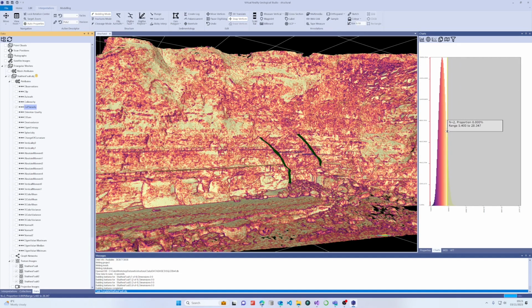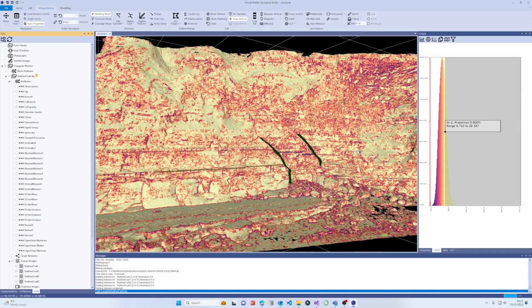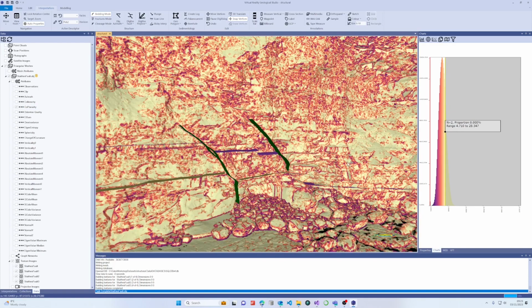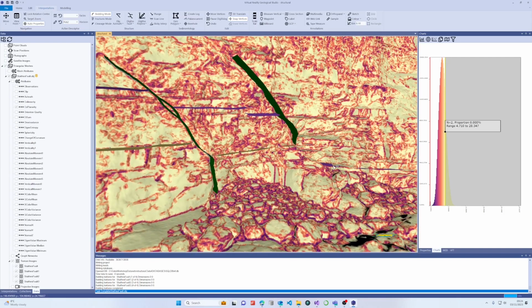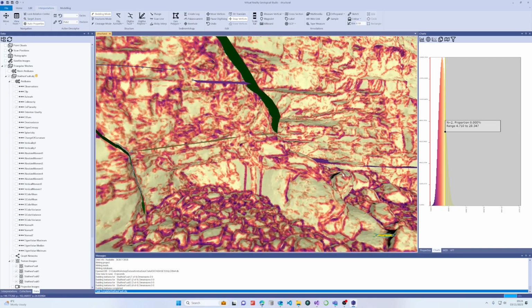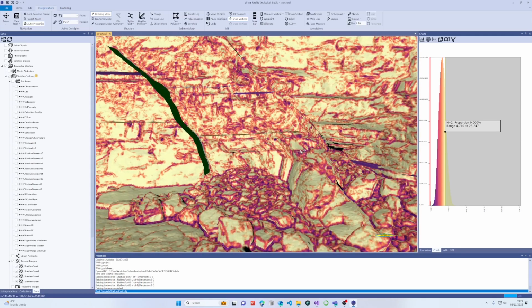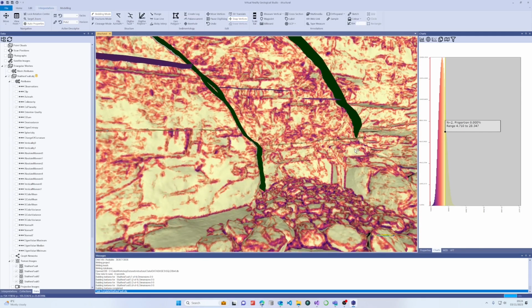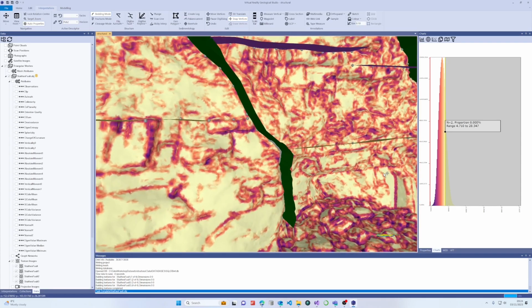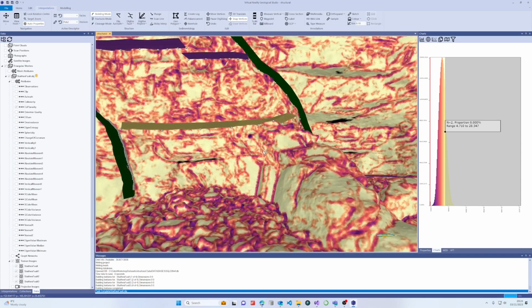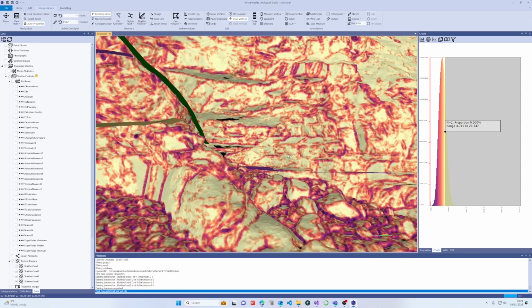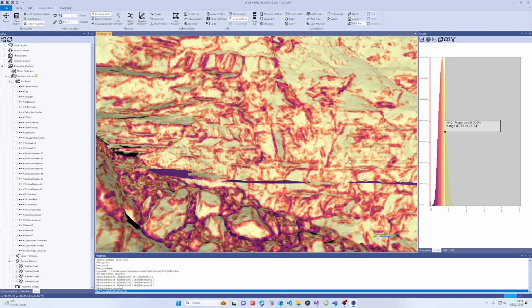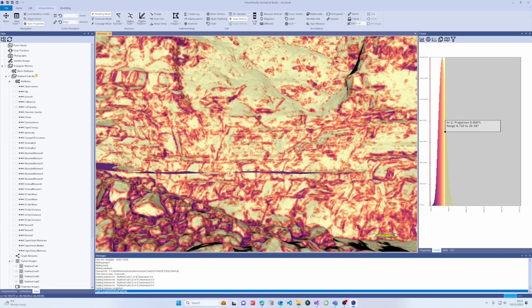And I'm going to drop my filter down to about somewhere around 4.5. Values of over 4 for coplanarity tend to be quite flat, and that is then a good way that you can use to sort of identify things that you think might be exposed bedding planes and fracture planes. For example, here there's a couple of distinct orientations that are being picked up, and we can see certain planes and orientations repeating over and over again.